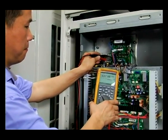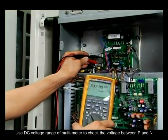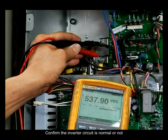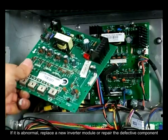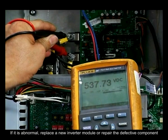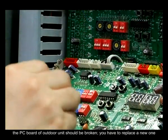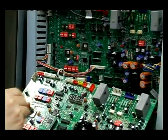Step 2. Use the DC voltage range of the multimeter to check if the voltage between P and N of the inverter module is about 540 volts. Confirm whether the inverter circuit is normal or not. If it is abnormal, replace a new inverter module or repair the defective component. After the above repairing, if the malfunction still exists, the PC board of the outdoor unit should be broken. You have to replace a new one.